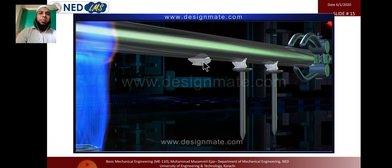So the dropping of this nail indicates the conduction direction, how fast the conduction is passing over here. The wax placed here in that position melts, and due to the melting of wax, the nails will drop down. So by this simple experiment, we can also compare two different metals. Like if we fix a brass rod, and compare it with copper, the faster the nail drops, the better conductor of heat it is.